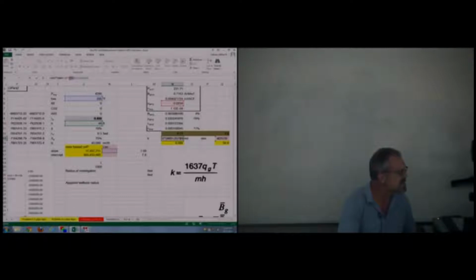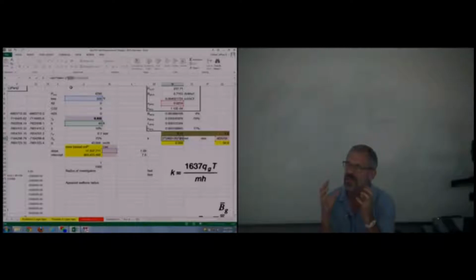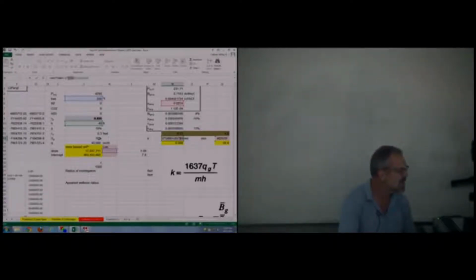We no longer have viscosity, but we have rate. The reason we didn't have rate before is we had a form of the equation for variable rate. We were plotting delta P over Q and looking for the change in that. So we actually have to put in a Q on this one. Now I've got my Q, my temperature, and my coefficient. Let's look at the denominator. It was calculating the slope, but I want to calculate my slope. And it's got h in there. So I get a permeability of 63.41.